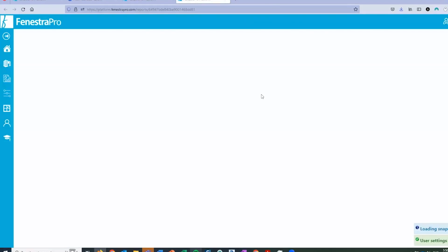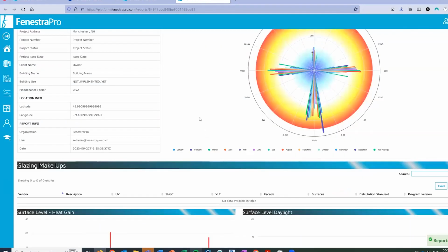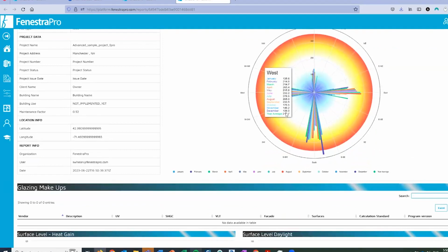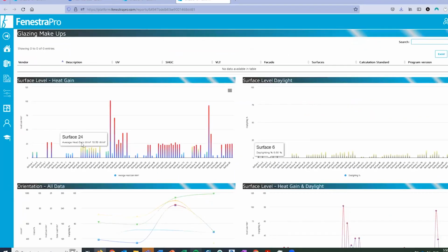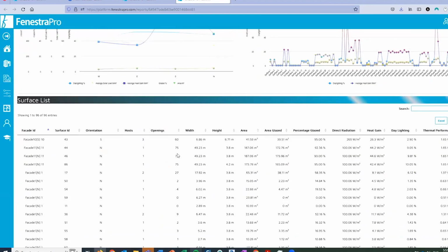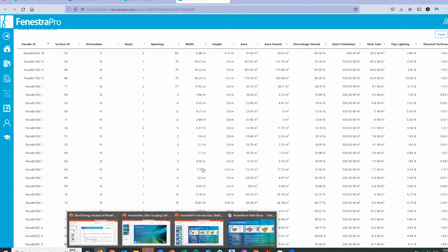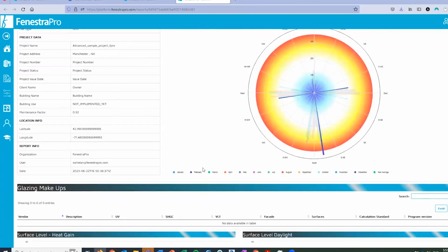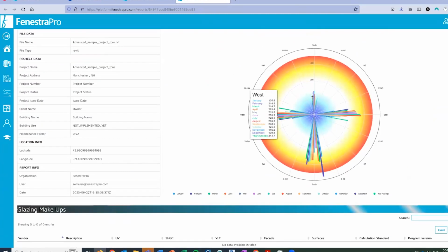So, exporting all of that information to your reporting platform and being able to dig in. This is all of the info that I just generated immediately from this model, very quickly. All of the climatic information, all of the different orientations, all the geometric info, glass to wall ratios, areas per surface, areas per facade, etc., massive amounts of information. And then getting into the properties and the materials. There's a lot there, as you can imagine.